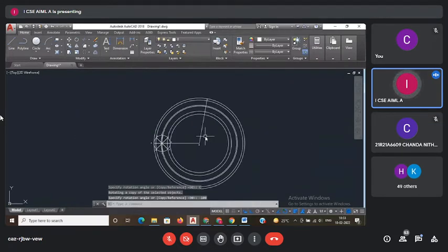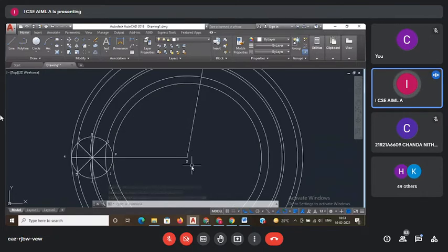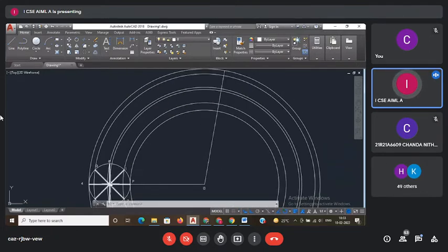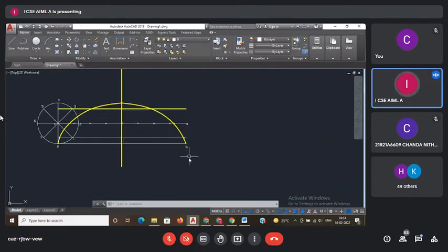Okay, I got minus 100. What is the need of this angle? Sir, what is the need of this angle means after complete one revolution of the rolling circle, it has to close the curve. Where it will close, that end point you know. That end point you have to identify it. In a cycloid, you know the end point. What is that end point? 157. That 157th point is your end point after completion of one revolution.